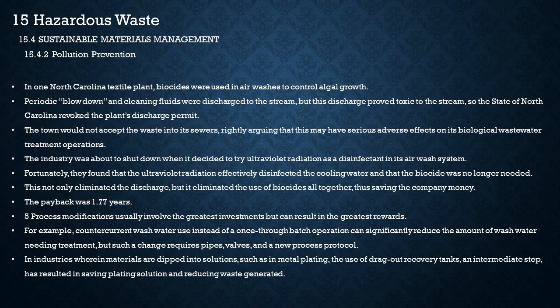Process modifications usually involve the greatest investments but can result in the greatest rewards. For example, countercurrent wash water use instead of a once-through batch operation can significantly reduce the amount of wash water needing treatment, but such a change requires pipes, valves, and a new process protocol. In industries wherein materials are dipped into solutions, such as in metal plating, the use of drag-out recovery tanks, an intermediate step, has resulted in saving plating solution and reducing waste generated.